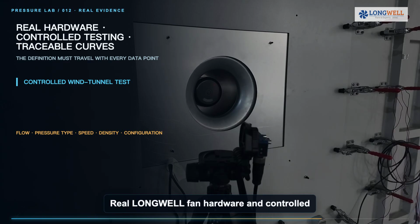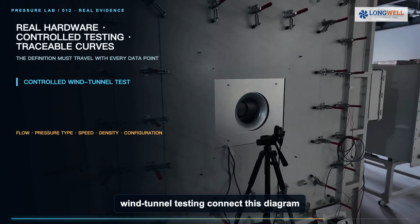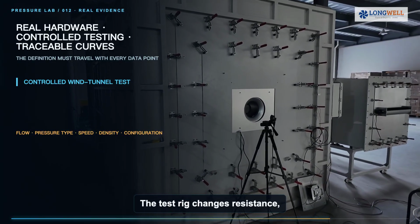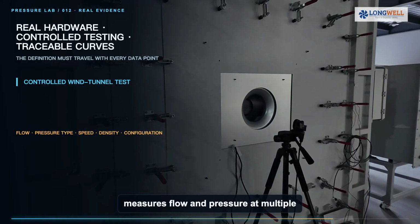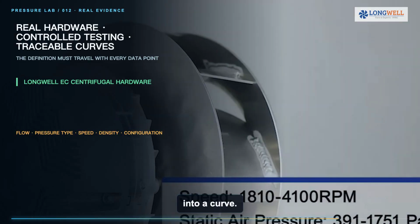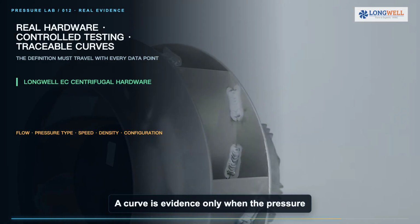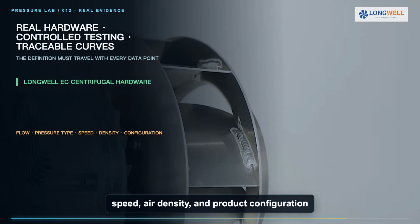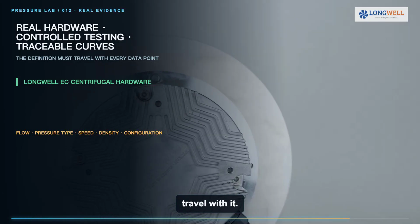Real Longwell fan hardware and controlled wind tunnel testing connect this diagram to physical performance. The test rig changes resistance, measures flow and pressure at multiple conditions, and turns those measurements into a curve. A curve is evidence only when the pressure definition, test arrangement, speed, air density, and product configuration travel with it.